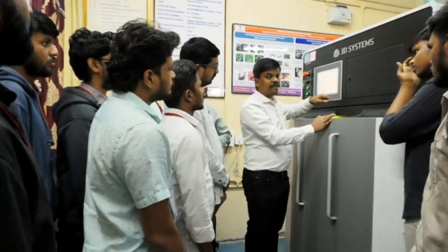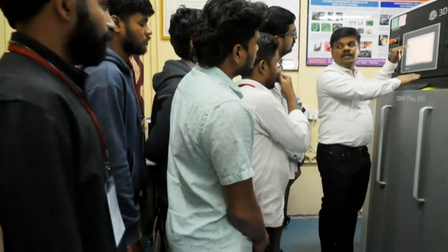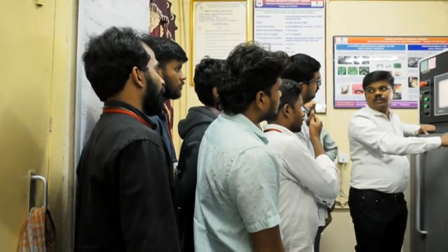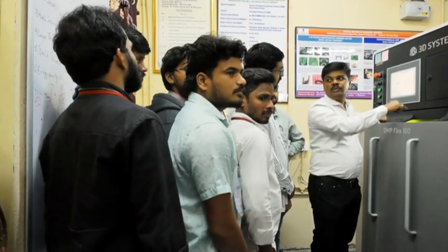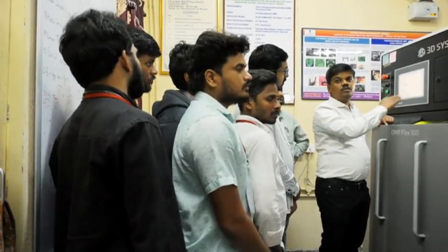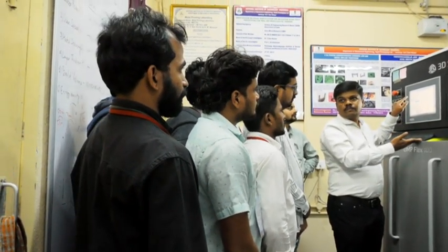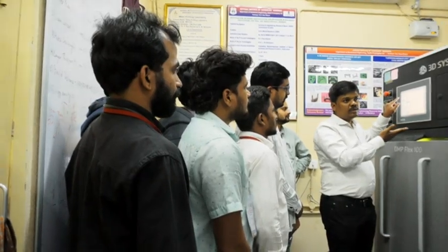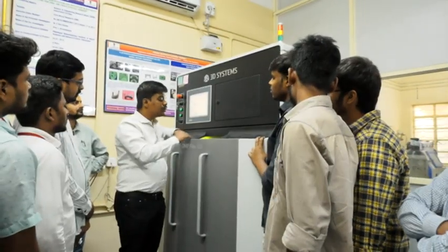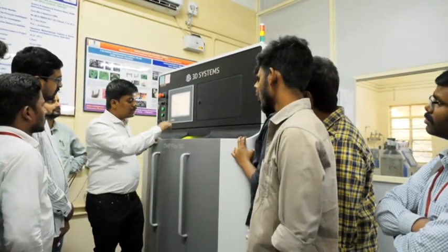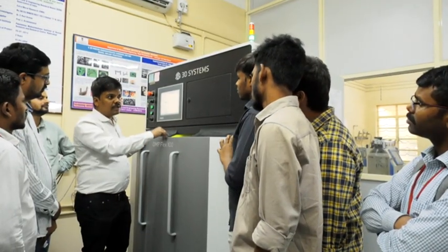Once the laser has sintered the first layer, the second layer of powder particles is distributed on the build platform area. The second layer is also melted or sintered. The process keeps repeating, and the build platform goes down by one layer height each time, and every layer of powder is distributed. If you see how the process works, every layer is melted, then the second layer of powder particles comes, and again it is melted.